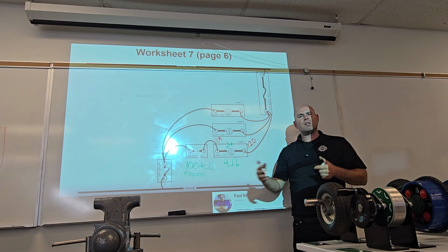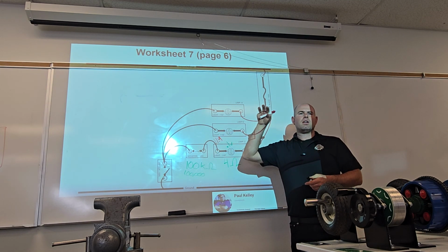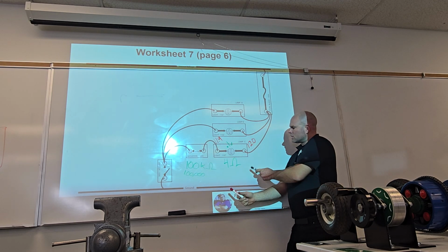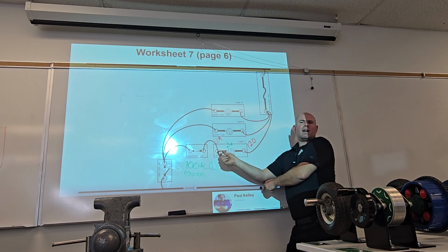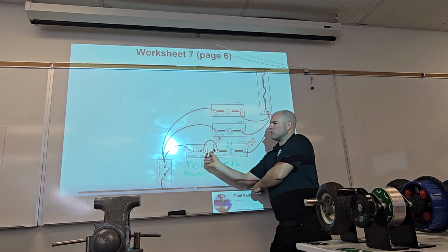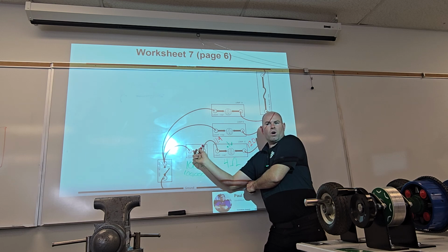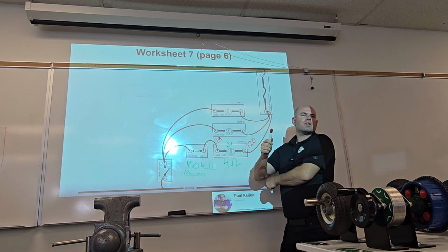But mathematically, I want you to just kind of understand it. And from a theoretical standpoint, I want you to understand it. So if I were to do the diagnosis and I were to get 12 volts and 11.9, you know what I know already? I know there's resistance here on the ground. Does that make sense? Where the resistance is, well, I have to do another test.